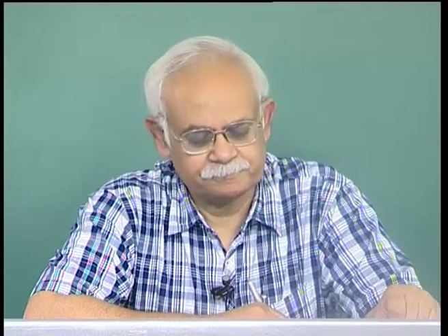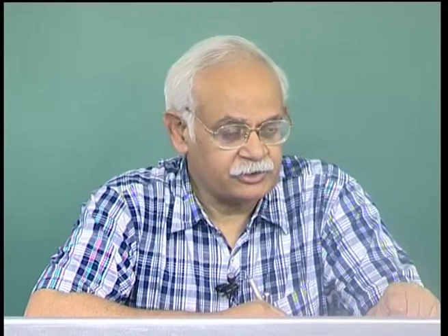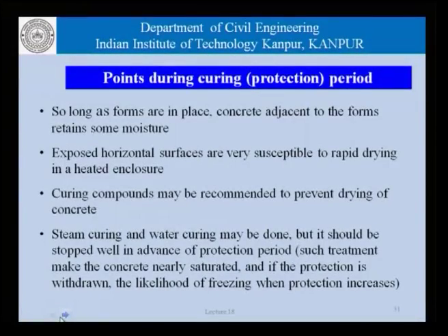So, it is a very, very difficult and a very thin line that an engineer has to walk to make sure that the concrete is appropriately protected at the surface. And therefore, sometimes it is prescribed that we use curing compounds to prevent drying of the concrete. Steam curing and water curing may be done, but it should be stopped well in advance of the protection period. Such treatment makes the concrete nearly saturated.